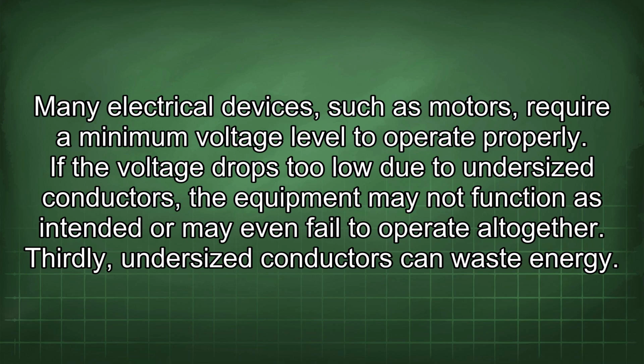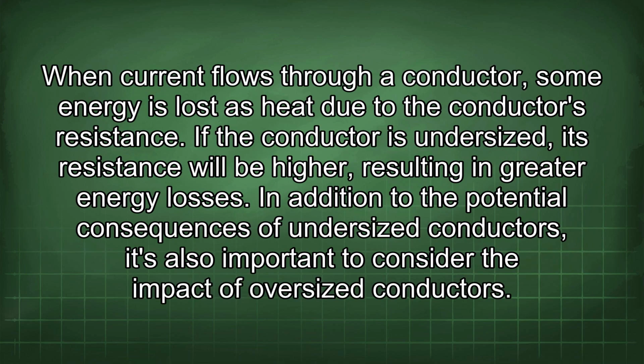If the voltage drops too low due to undersized conductors, the equipment may not function as intended or may even fail to operate altogether. Thirdly, undersized conductors can waste energy. When current flows through a conductor, some energy is lost as heat due to the conductor's resistance. If the conductor is undersized, its resistance will be higher, resulting in greater energy losses.